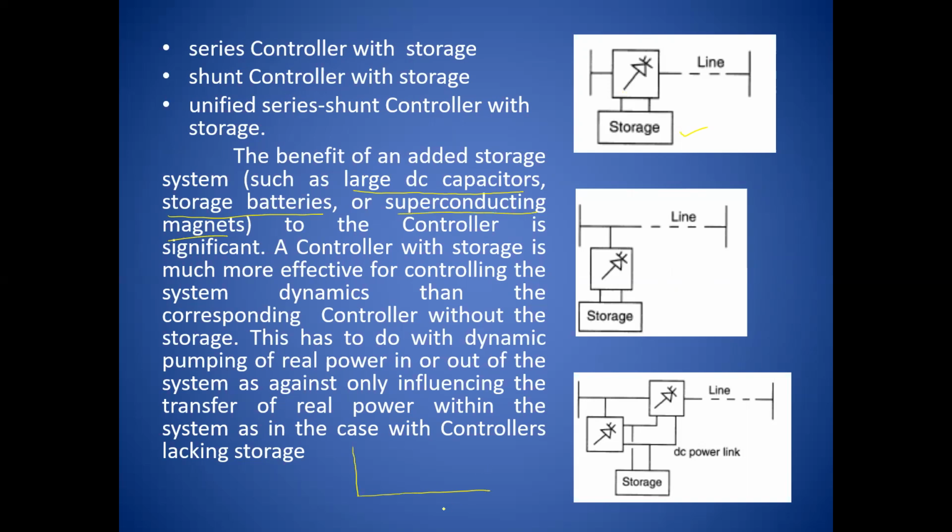Okay, so this is the time and this is the magnitude of transients. During the transient of about 1.5 cycles, after that there are oscillations in the system. So 1.5 cycles may be considered as a transient, whereas the rest of the time, the way the power system reaches the new equilibrium position, say delta 0 to delta 1,